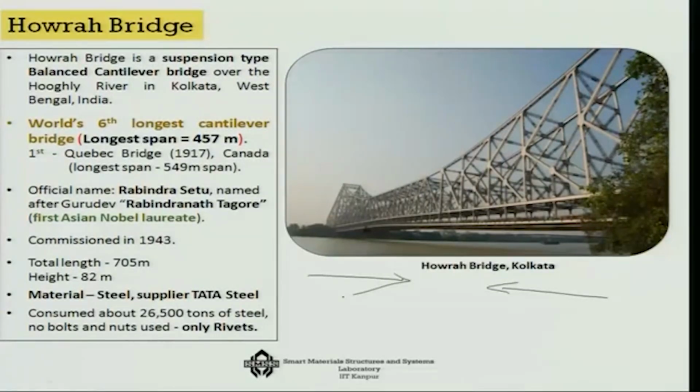Basically, due to the application of load in both cases, there is a bending that you would not see in the cast iron bridge over river Severn. This bending means that if you take any member, the stress profile on the member has both tension as well as compression.